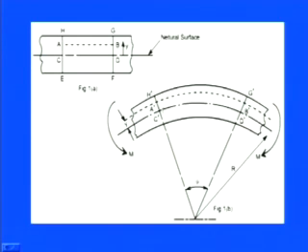This is due to some extension, and we can easily formulate this extension because we know that this distance is r. The neutral axis distance, as we define it, is the radius from this locus point to the neutral axis. So this distance is r, and we defined in the previous section that the AB section has a distance y from CD. So this one is the y. The total distance for the curvature path is nothing but r plus y, and then this theta is there, so we can define it with the radius and arc definition.